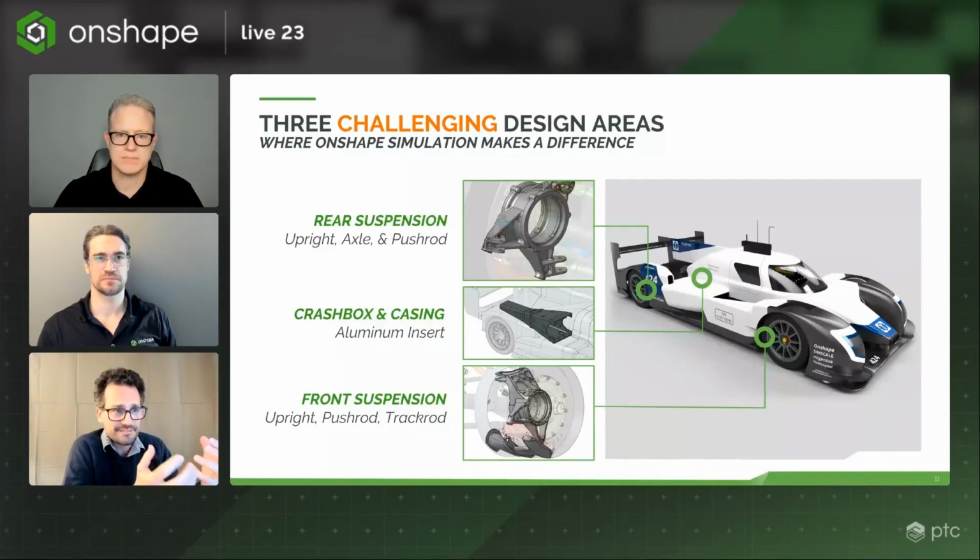We do thermal analysis. Electric powertrain, as we know, heats up quite quickly. The lap is 5 minutes. So as an example, the battery starts as cool as we can, maybe 15 degrees, and at the end of the 5 minutes, we need to make sure it stays below 70 degrees. And we have accurate simulation of what the battery temperature will be. Again, all of this is important to design and dimension, for example, the cooling system of the car. These are only two examples.